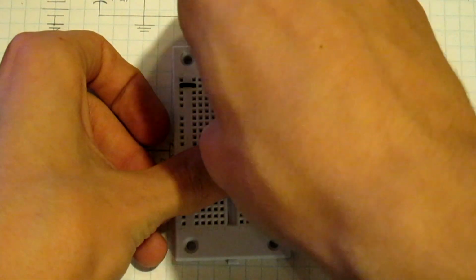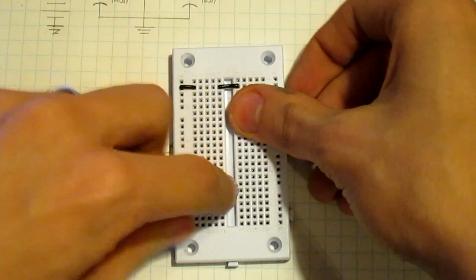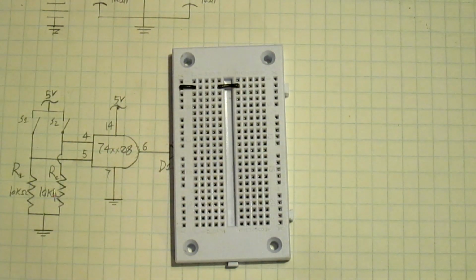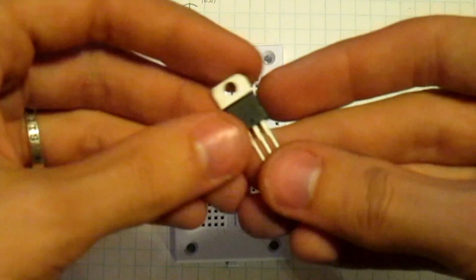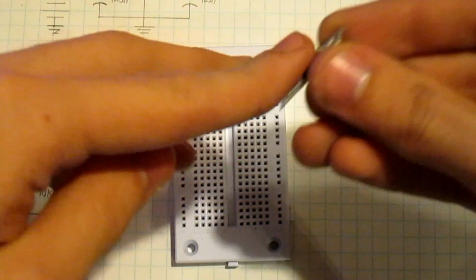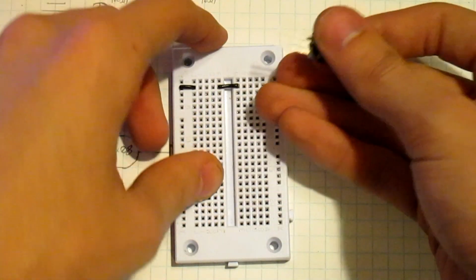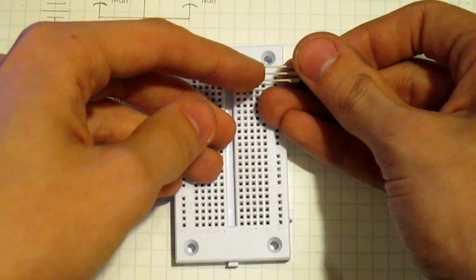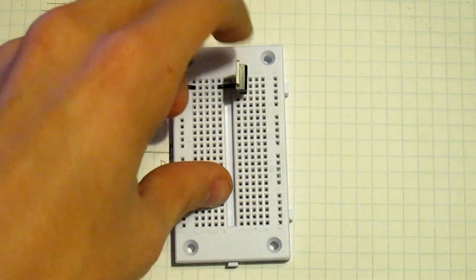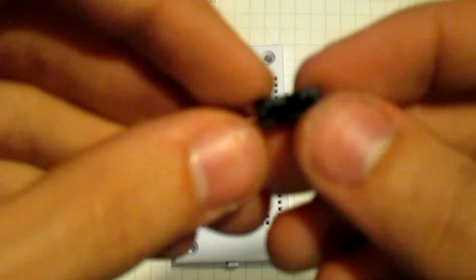I'm going to put another black wire which connects over the channel, because this channel separates stuff on each one of these rows. It separates the whole thing. You want to grab a 7805 voltage regulator. It'll say it right on the front, and you want to stick it so that the back, the flat side, is toward the channel all the way on the top. So the black wire will be on the same row of holes as the middle leg on this integrated circuit. Next, you want to grab a 10 microfarad capacitor.